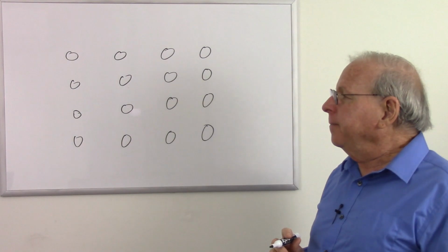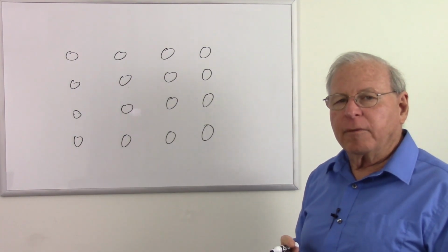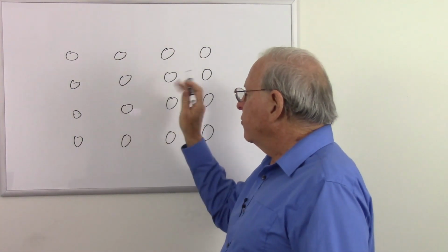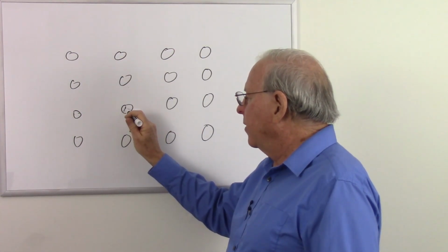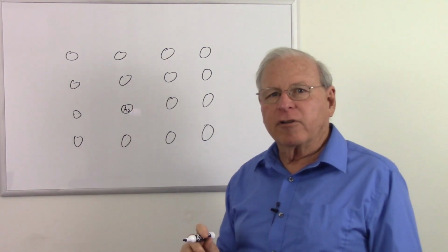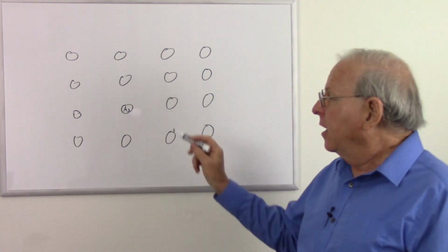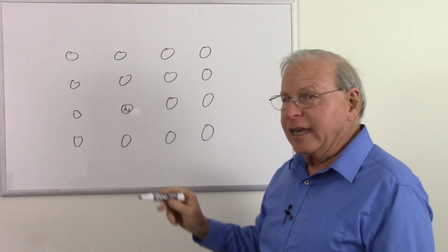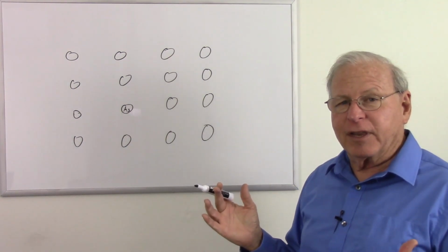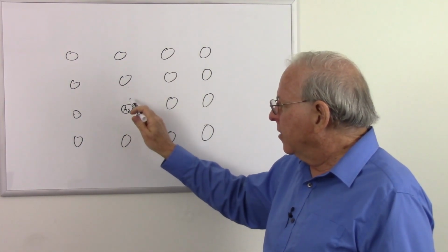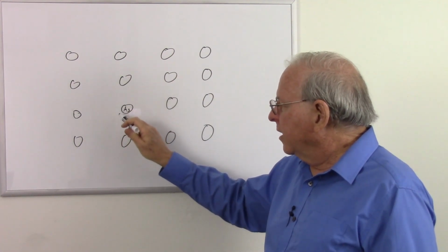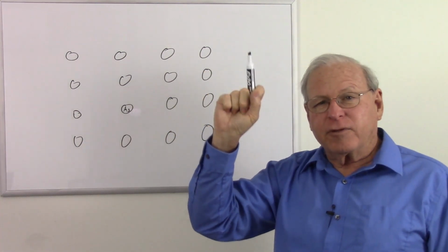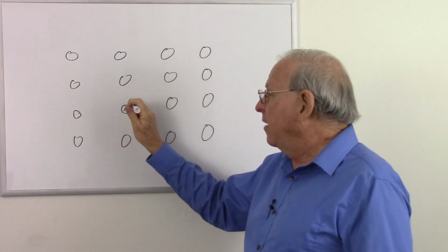But what would happen if we contaminated this with a little bit of something, let's say arsenic? Let's say these are all silicon atoms, but I'm going to put an arsenic atom here. And do you remember how many electrons arsenic has? It has 5. So I have 8 electrons around all these atoms, except this arsenic ends up with 9 around it because it has a 5th electron. So this arsenic atom gets 4 of its own electrons, 4 electrons from all of its surroundings, plus 1 left over that doesn't fit. So we have a free electron.